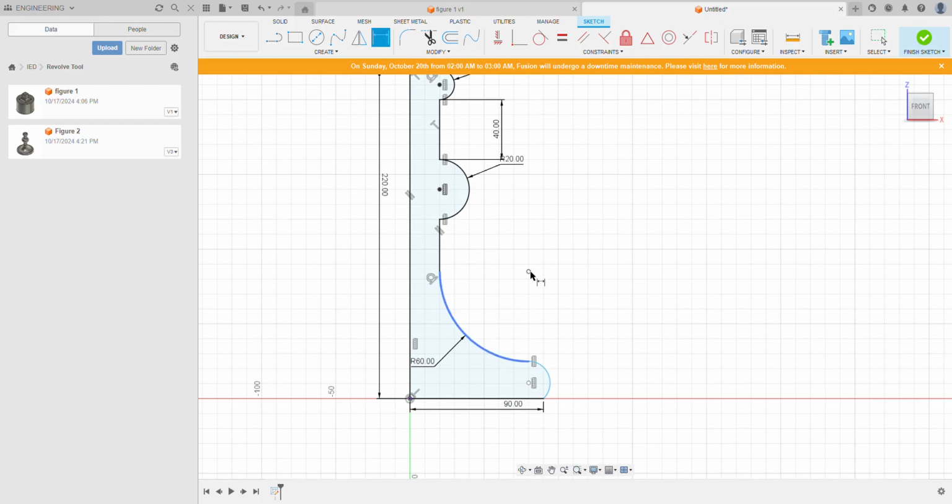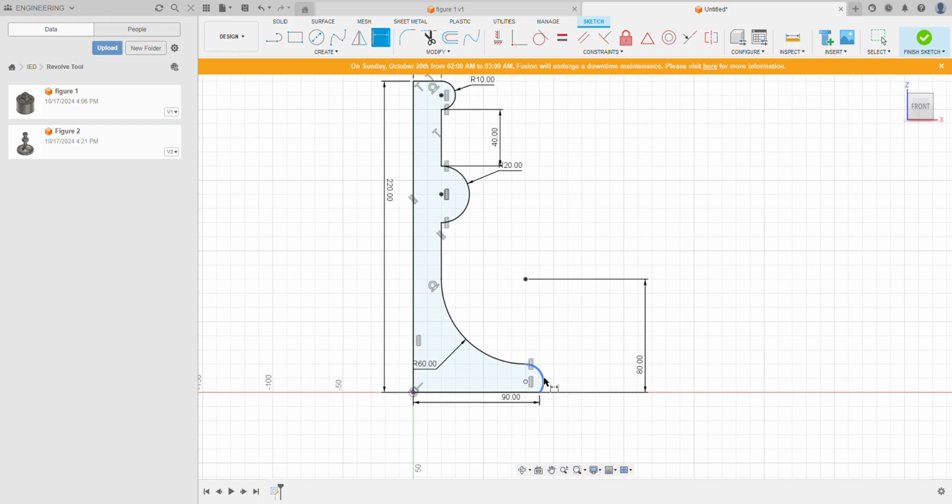We do have a dimension from the center to the very bottom of our candle wick. This is actually decently close, but it's only supposed to be at 80, not 85. And looking at our sketch, we only have one more blue line. And ironically, because of all of the constraints we've done, we didn't even have to make it.